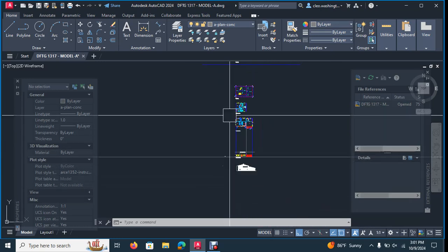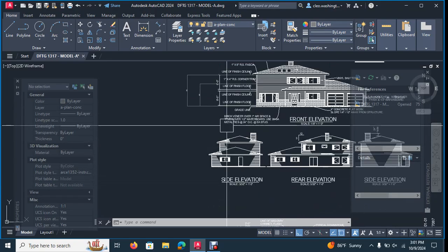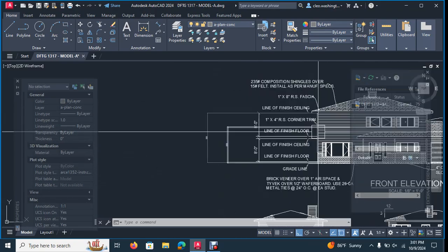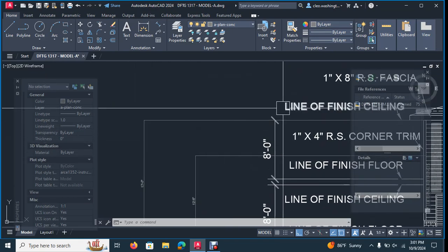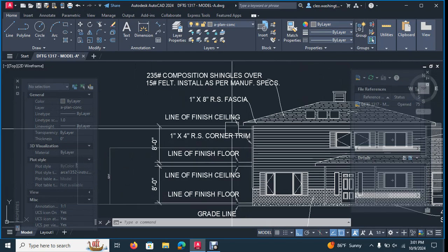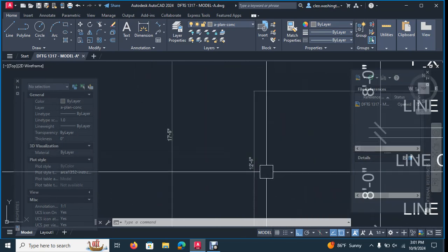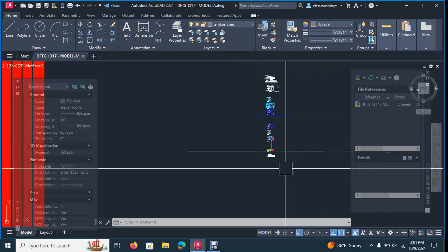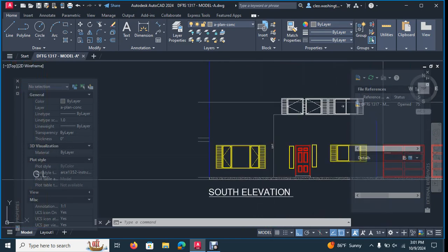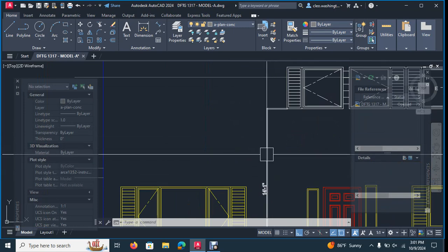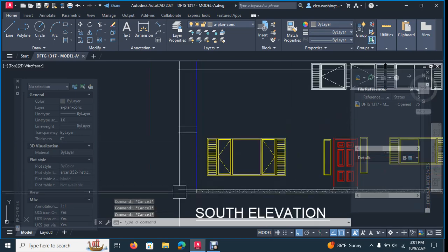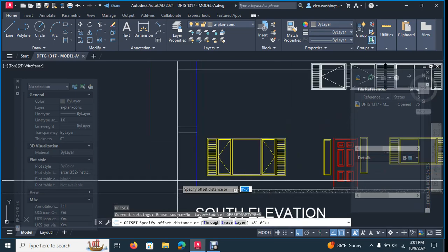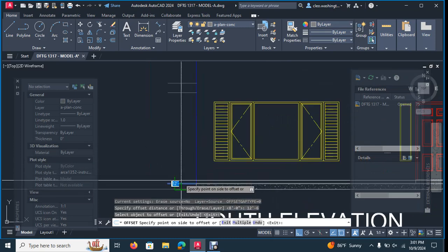We'll just draw it. So right now we want to make sure that the window sill is at 12'6", and we want to make sure that the bottom of the fascia plate, which is this guy right here, is 17.5. So 12'6" and 17.5. So we just have to keep it simple. And then if it doesn't work, we'll make some adjustments. Okay. So right here it's saying 14.1. So let's go offsets 12'-6". So offset this line 12'6".